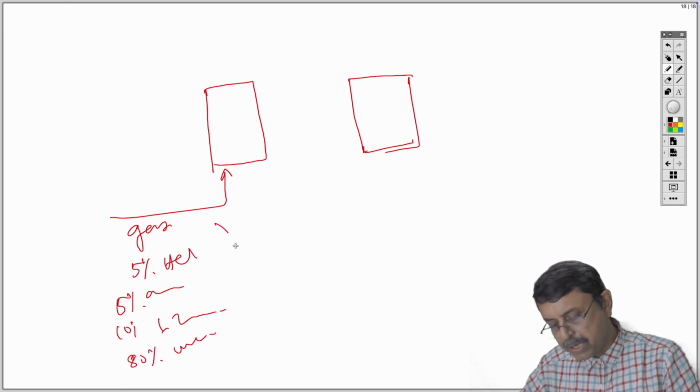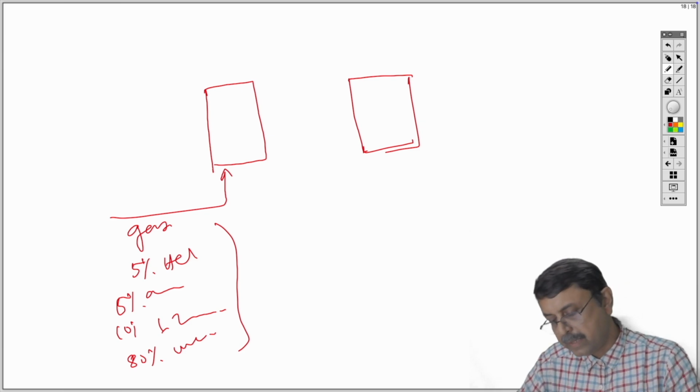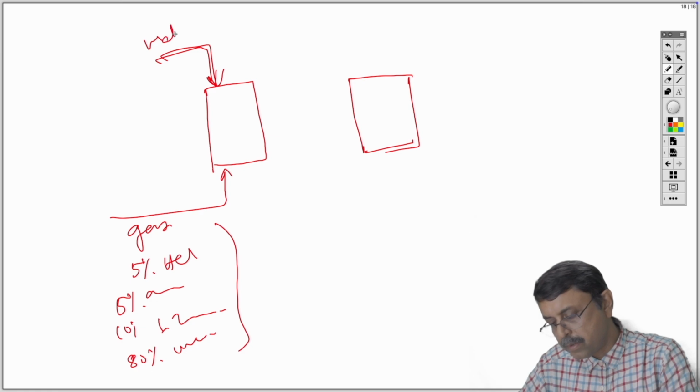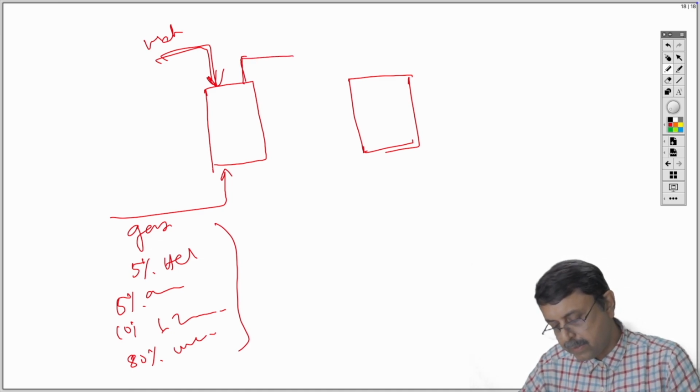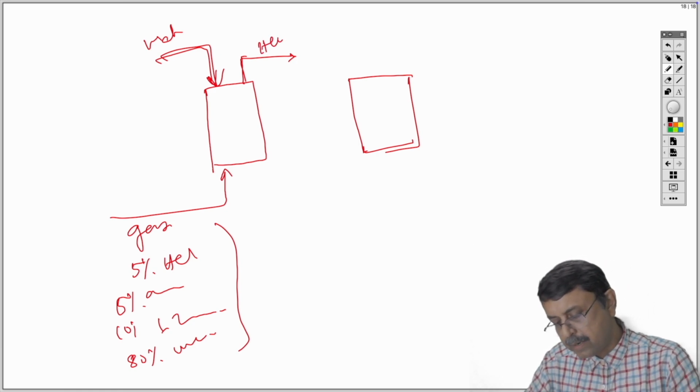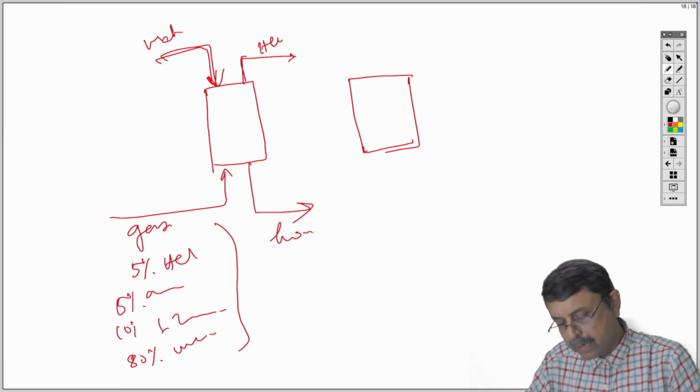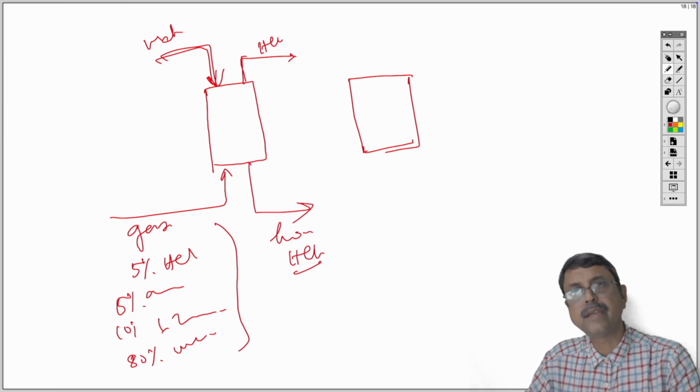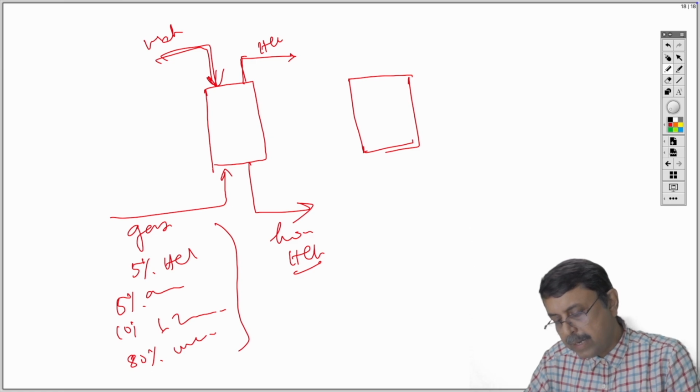Its temperature, pressure, and flow rate has been given. Water is poured from the top, okay, pure water, and some scrubbing occurs over here. The gas stream, which is also having some HCl, because all of HCl cannot be removed through water. Here water will come, in which majority of HCl will be carried forward, and lean gas will go and pass